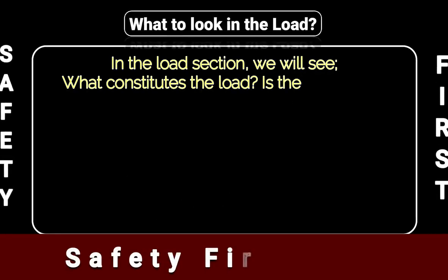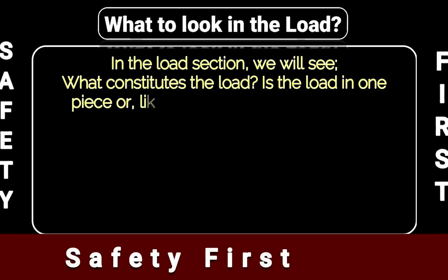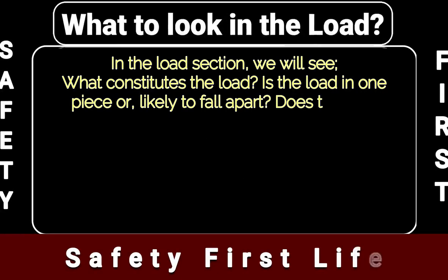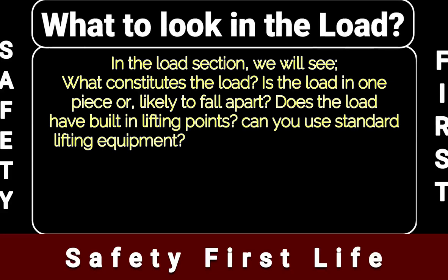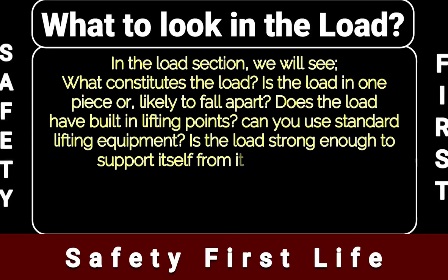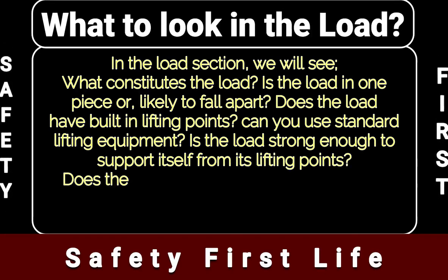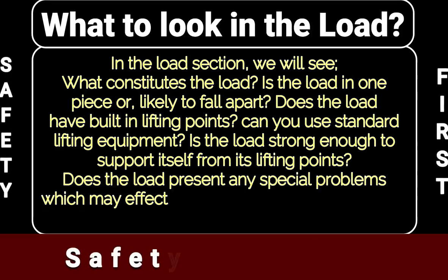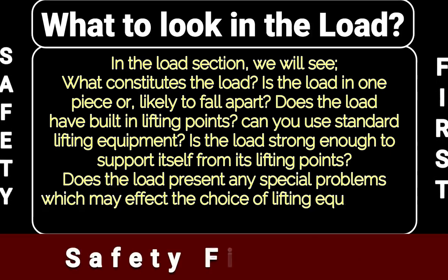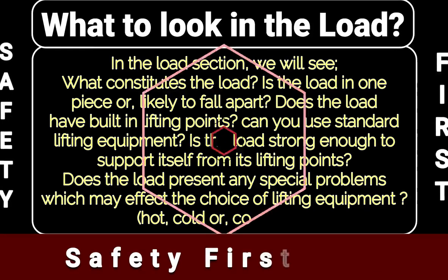In the load, we'll see what constitutes the load. Is the load in one piece or likely to fall apart? Does the load have built-in lifting points? Can you use standard lifting equipment? Is the load strong enough to support itself from its lifting points? Does the load present any special problems which may affect the choice of lifting equipment, maybe hot, cold, or corrosive?